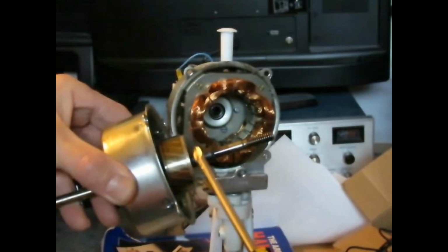Magnets have two poles, north and south. When a certain part of the metal mass cuts through the north pole of the magnet's flux lines, current flows in one direction, which we'll call positive. When that certain point cuts through the south pole of the magnet's flux lines, it causes the current to flow in the opposite direction, producing a negative current flow. As it keeps spinning, the current flow changes direction in unison with the rotating metal mass. Thus, you have alternating current, or AC.